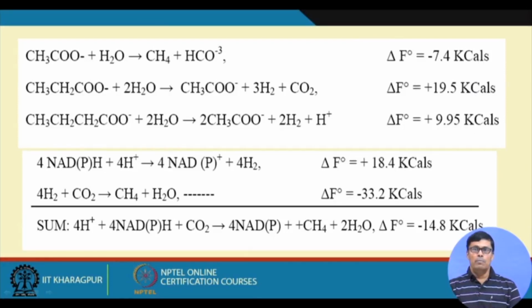So, it has been observed that when you operate any kind of anaerobic digester for a longer period of time, there will be accumulation of propionic acid in the reactor. In the long run, as you operate for longer periods, propionic acid accumulates in the reactor because the propionic acid degradation will be very poor.